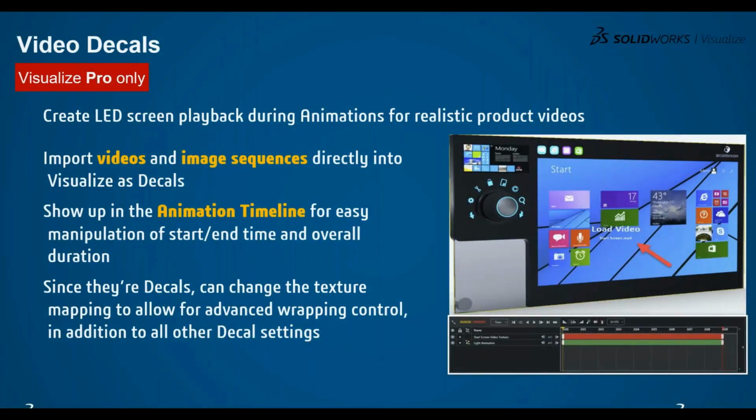Now let's go to the video decals. This is a really innovative capability of using videos and image sequences in SolidWorks Visualize, right? You can easily import your videos and image sequences directly as decals. These features enhance your project by allowing dynamic content to be integrated seamlessly. Let me show you how it actually works.